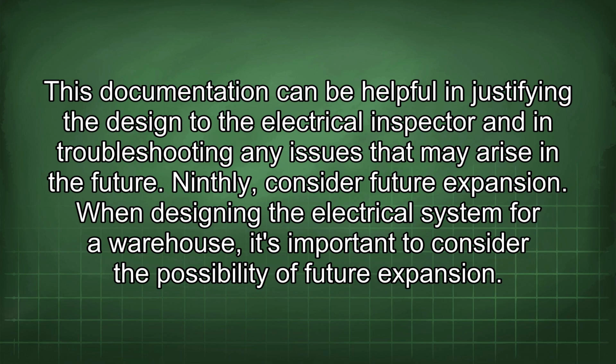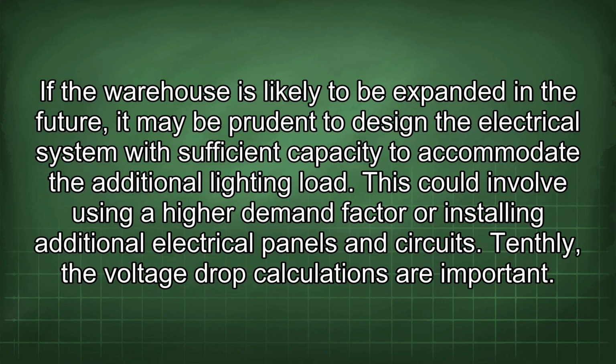Ninthly, consider future expansion. When designing the electrical system for a warehouse, it's important to consider the possibility of future expansion. If the warehouse is likely to be expanded in the future, it may be prudent to design the electrical system with sufficient capacity to accommodate the additional lighting load. This could involve using a higher demand factor or installing additional electrical panels and circuits.